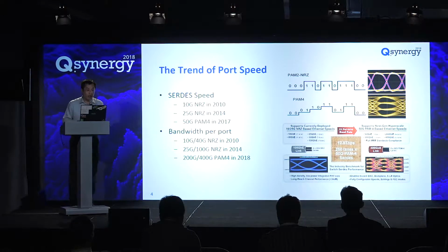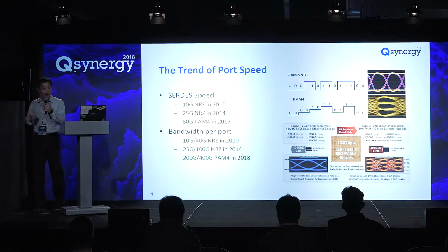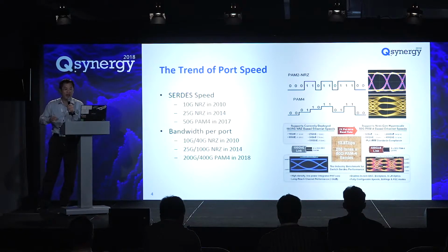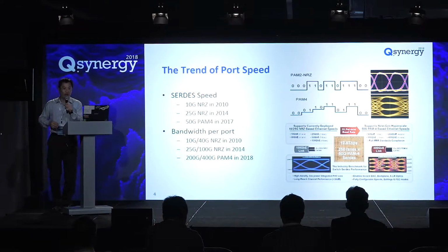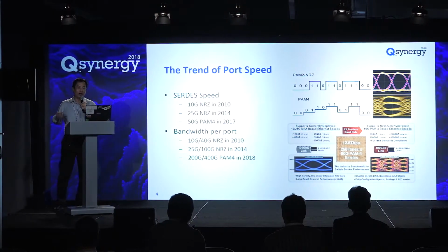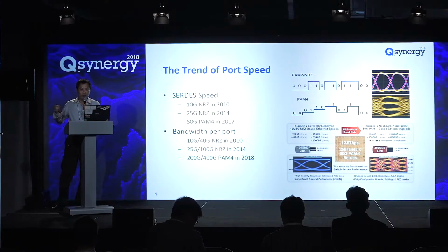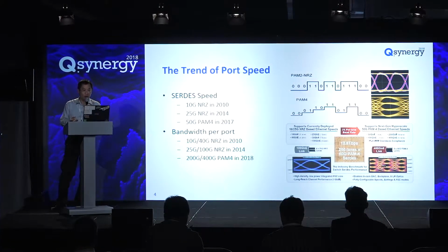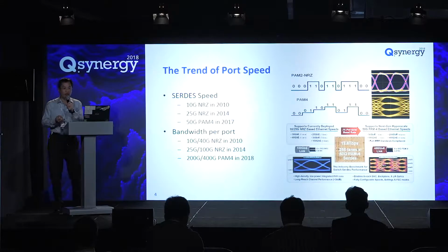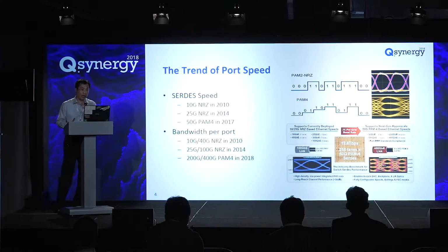So this is another trend, about the port speed, that creates a lot of challenges, especially handling the signal quality on a certain level of PCB quality. And we don't want to put extra components in to increase the signal quality. Just keep the board simple, but still keep the signal integrity without compromising the quality. So this is the trend of the port speed.